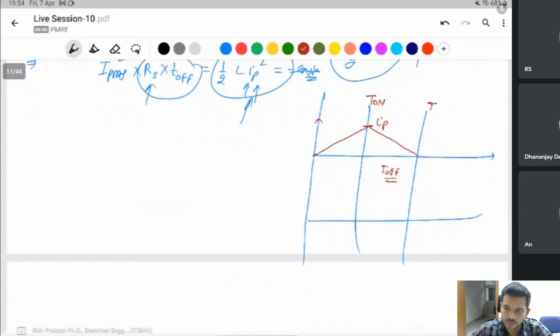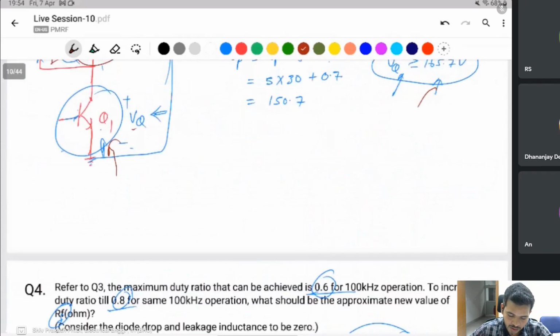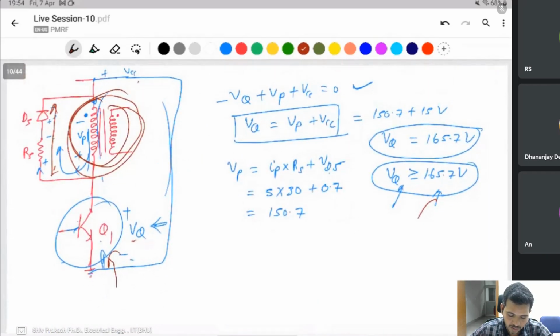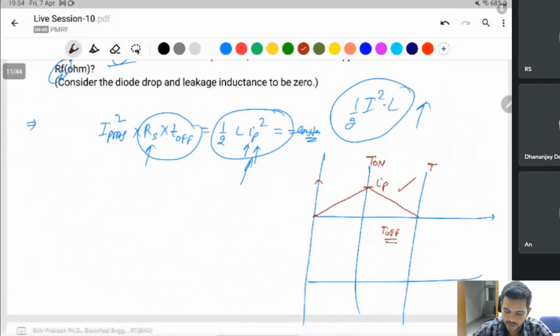So the inductance value of the winding will form, while discharging, an RL circuit. Then we have to take the peak value when it starts decreasing for calculating the voltage drop. Sir, this is a different thing, but here I only take ideal cases, like a maximum current flowing linearly and decreasing linearly. If it is exponential, then the calculation, the RMS value, is very complicated.